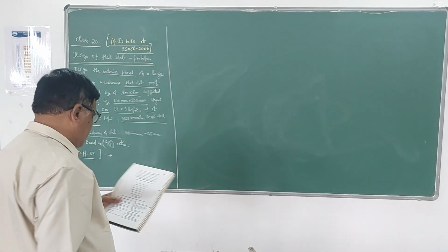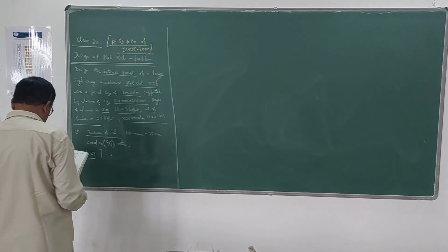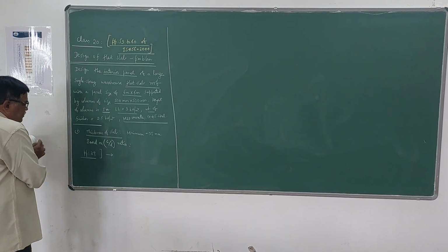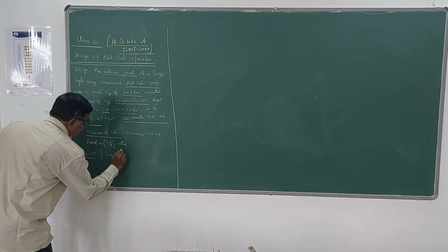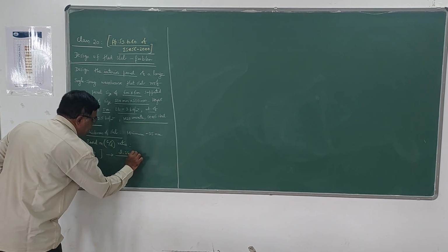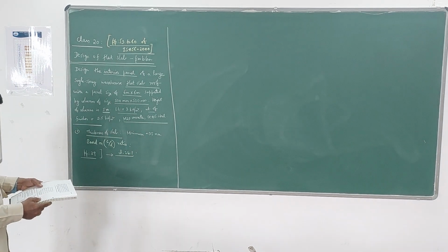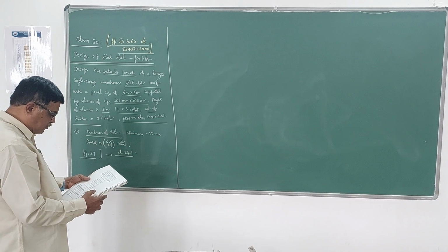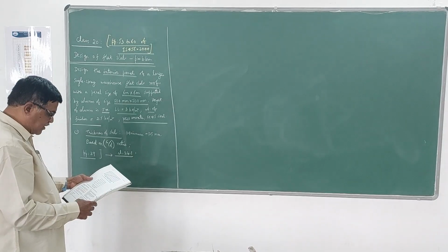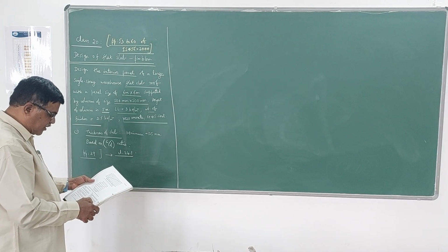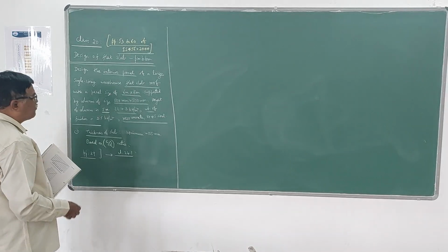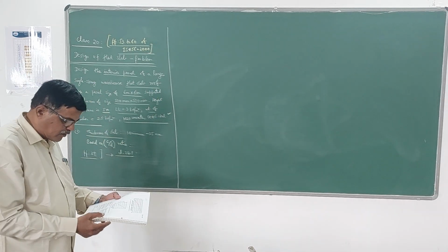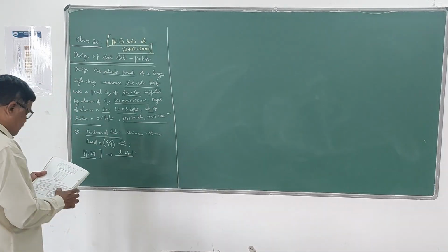What it tells is, for two-way slabs, you can see that it is available in clause 24.1, page number 39. He has given the L by D ratio for two-way slabs of shorter spans up to 3.5 meter with mild steel reinforcement, up to loading of 3 kN per meter square. When you are using Fe415 steel, that value is a little bit reduced. So we have to multiply that value by 0.8. That also he has given.